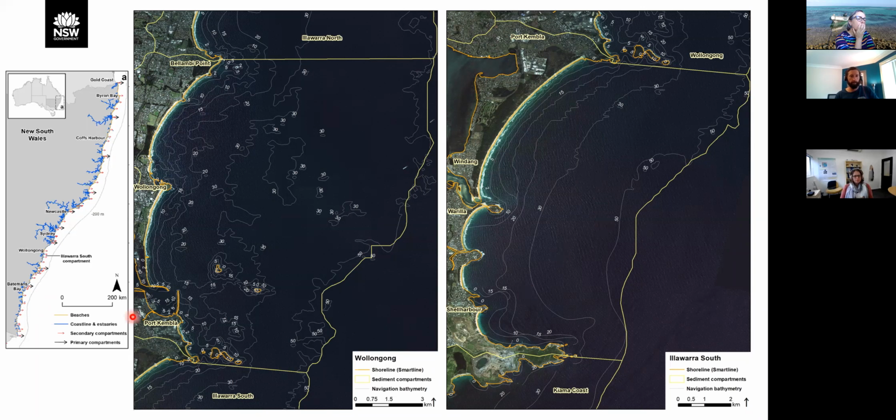So before our program, our understanding of the coastal seabed was relatively poor. It looks detailed here, and is detailed here, because there's a port right here. So obviously navigation, there's some islands and reefs. So it's been surveyed here in detail in terms of the bathymetry. But even as we go south into the next compartment, the data becomes more vague and generalized. And these contours are based on a decreasing density of soundings for navigation bathymetry. Obviously not much known about the sediment and reef distributions.